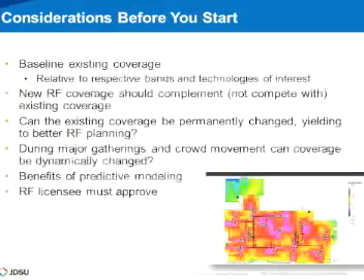But also, in terms of considerations before you start, think of the benefits of predictive modeling. Often, by putting up temporary transmitters and antennas, you can better model the actual environment that you're putting this distributed antenna system into. But ultimately, the bottom line and the last item is that the RF licensee, meaning the service providers, must approve whatever you're doing because it still is licensed spectrum that they own.